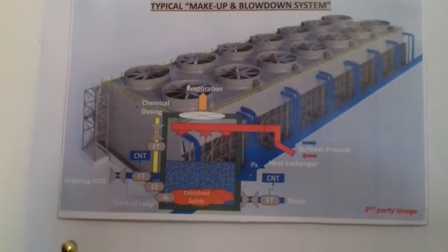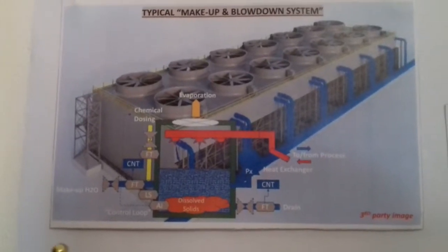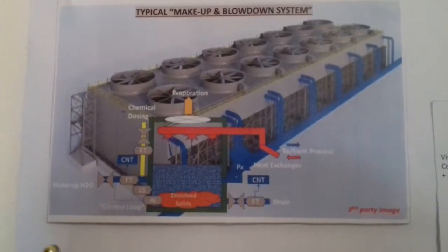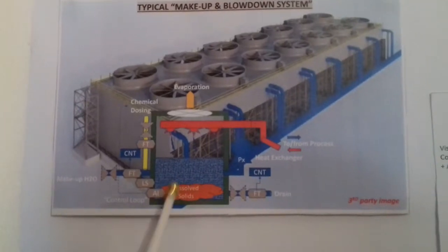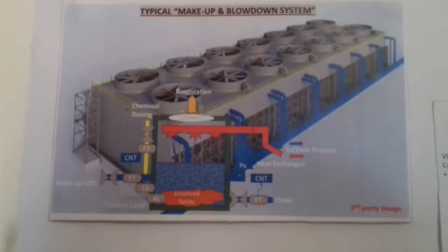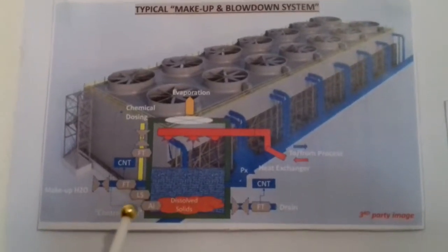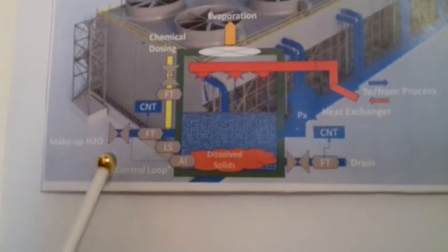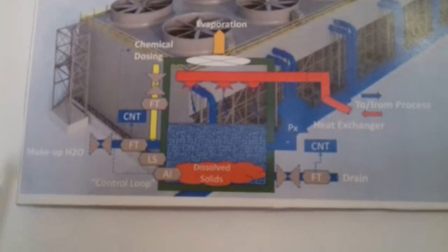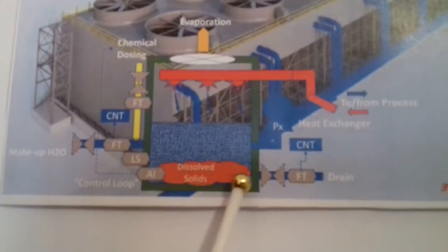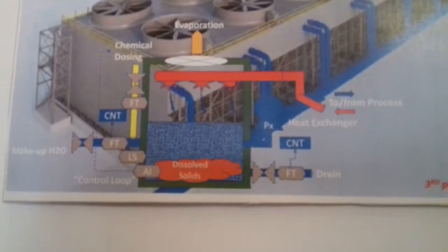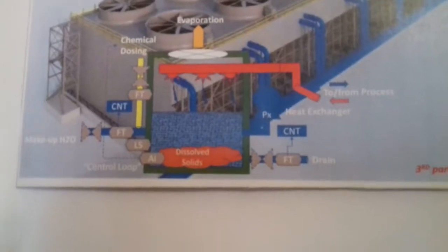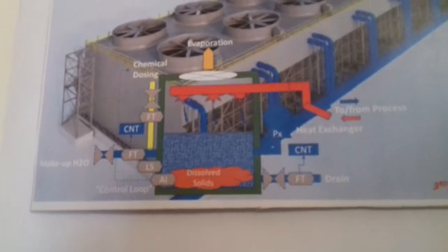If the system is remotely situated, then you will find more and more chance of having overruns of your water, where the system doesn't switch off. This obviously leads to lots of cost depending on your flow rates and the consumption rates per kiloliter of your water. The next thing to notice is your drain valve might also be left open manually by operators. So what I've done is I've designed a system. If we look at the second slide, it shows you the architecture.